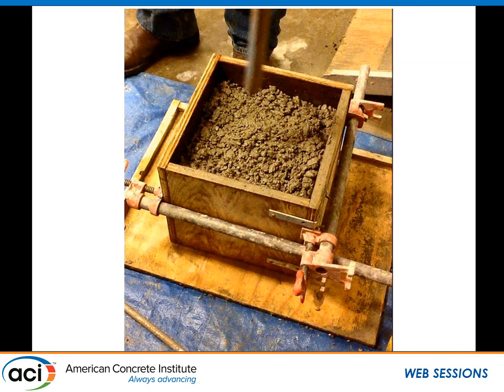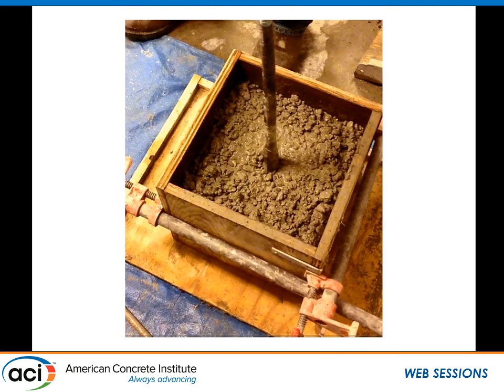This is what it looks like. So this is the concrete. You can see it being held in place. You see the vibrator coming down from the surface. And once it hits it, you can see the vibrator is influencing the concrete. That's called the sphere of influence, right? Sphere for you concrete nerds out there, right? And as the vibrator goes down, you'd like that sphere of influence to be larger. You'd like it to actually disturb the concrete, actually consolidate it all the way to the edges.